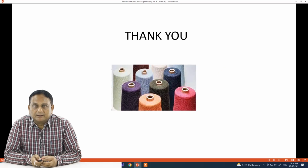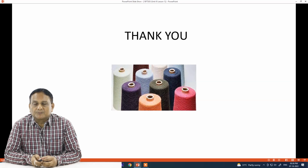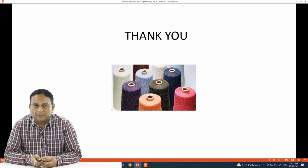As we can see, different varieties of yarns are available in the textile industry, like spun yarn and filament yarn. These are the two basic classifications. So we have seen the direct system and the indirect system. The indirect system is applicable for the spun yarn category, and the direct system is applicable for the filament yarn category. In this way the count, or the thickness or fineness of the yarn, is calculated, and from it we can get an idea of what type of yarn has been used in a fabric.